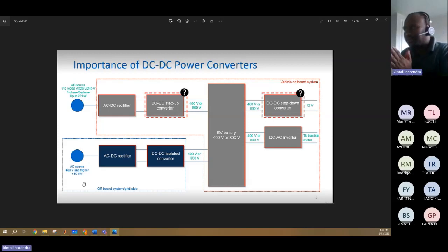One thing you need to remember is that whether you are using your home supply or the onboard circuits of your vehicle, the conversion is the same. You always take the AC power supply, convert AC to DC using a rectifier, and then boost that DC to the level of your battery in order to charge it.